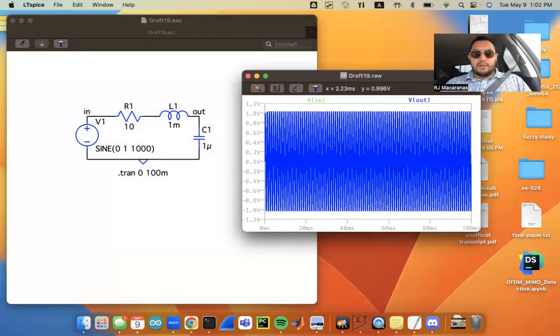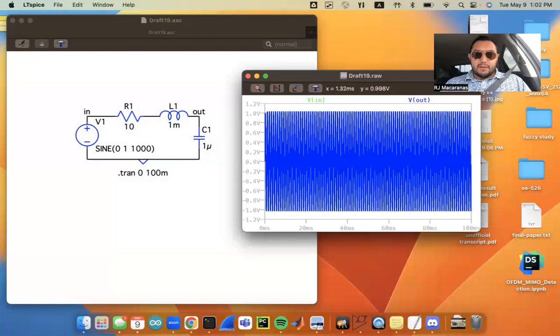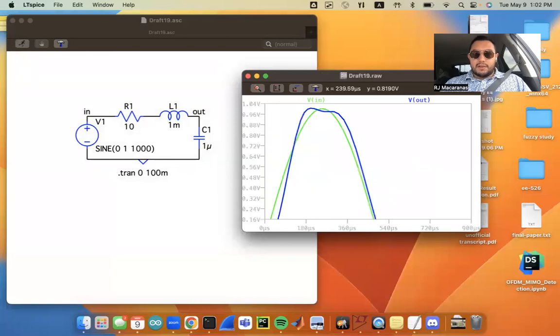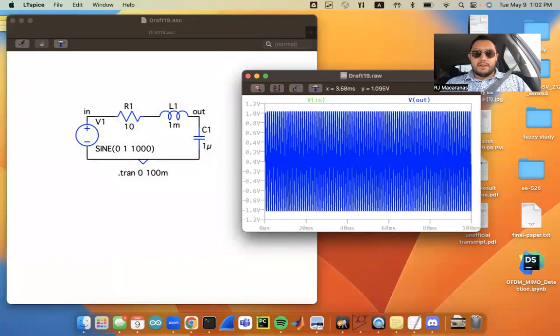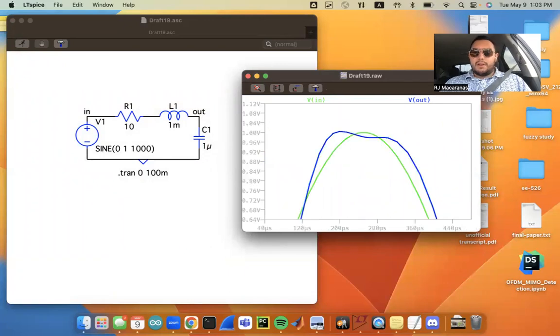And another thing to notice here, right? So you can kind of vaguely see that, well, we'll just zoom in here. You can see that here, the voltage is leveled out. This is what we refer to as steady state, right? So in the beginning, we have what we call transient response, right? Where the sinusoidal input is still kind of having some impact on the circuit, hasn't leveled out yet. But here, we've reached steady state. So, right, we don't want to measure the peaks here. We want to look at when we're in steady state.